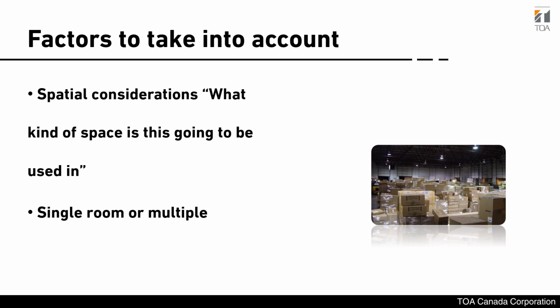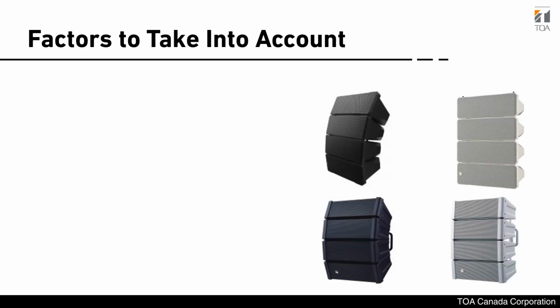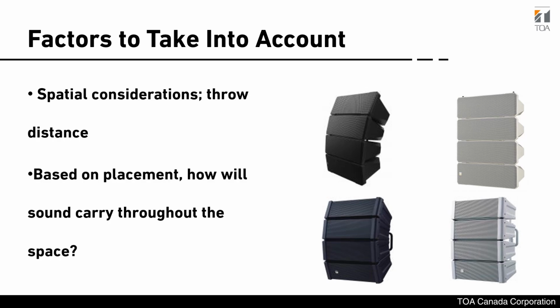Obstacles, walls, furniture, and layout affect sound reflection and absorption, impacting speaker placement. Choosing the right speakers depends on these factors to ensure clear and even coverage. Distance is another key consideration related to space, as sound loses power over long distances and as such requires high levels of amplification and excellent pattern control to produce adequate volumes throughout the space.